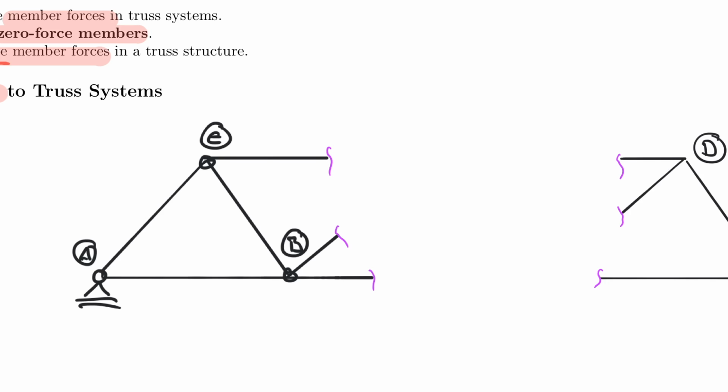So I will now introduce my internal forces, which are only normal forces, just like we talked about before. I have a normal force in line with each member, and similar to the method of joints, they are assumed to be in tension first.